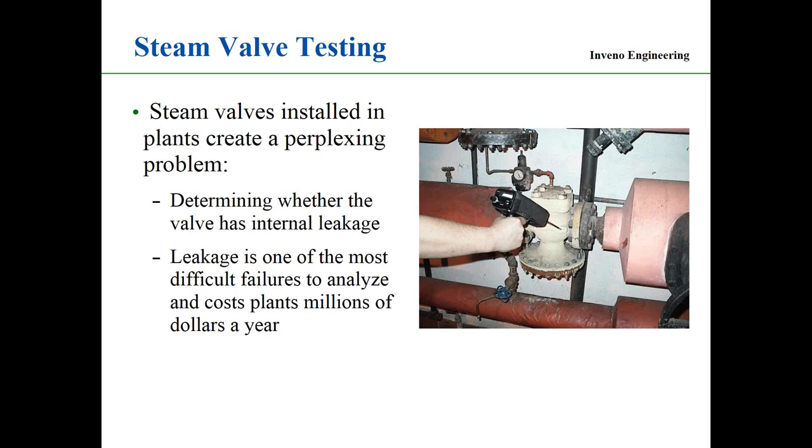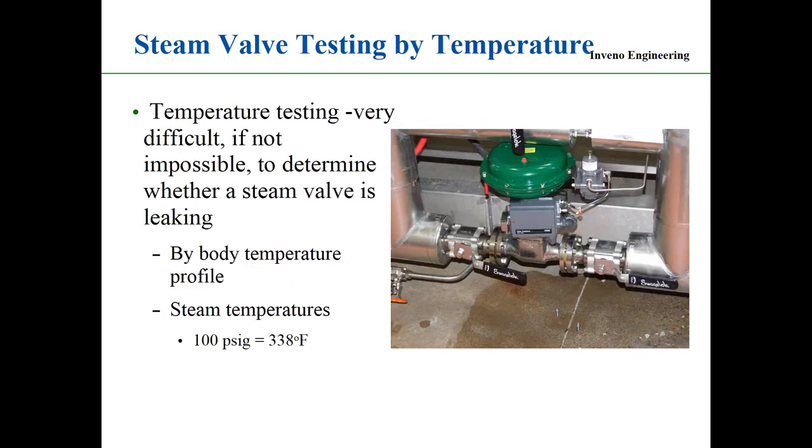You know, by going up and saying, geez, the valve is hot on one side, hot on the other side, that doesn't really work. Temperature, because we talk about energy and everything else today: with 100 psi coming into the inlet of the valve, it's going to be 338 degrees Fahrenheit.